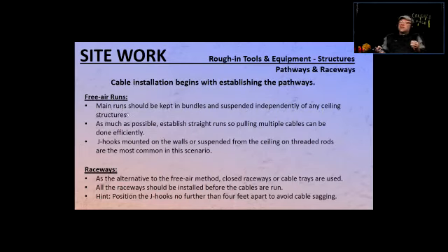What would be the most used ceiling structures? It would be the drop ceiling. See, in the building, you have the floor, then you have the space you walk in and breathe the air in. And then you're going to have a ceiling, usually consisting of ceiling tiles that are suspended on some metallic grid. Above the ceiling tiles that you can pop and take a look in, there's going to be ceiling space, or plenum. And that is going to be topped with the concrete slab, so it's called the true ceiling. It could be the bottom of the floor above, but here's the ceiling that we're talking about.